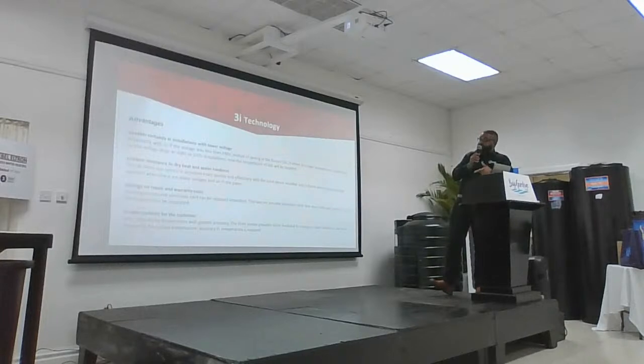So with this technology, it has an air detection. If there's air in the system, with any system that can cause a dry fire, which is burning the element. With this sensor, it will detect air in the system and cut you off via a red light on the board, right?